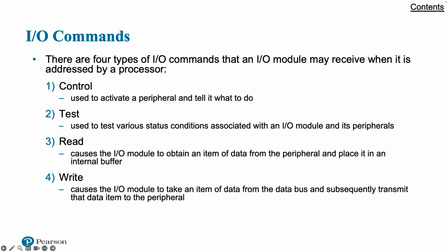Next, we have test. It is used to test the various status conditions associated with an I/O module and its peripherals. The processor will want to know that the peripheral of interest is powered on and available for use. It will also want to know if the most recent I/O operation is completed and if any errors occurred.